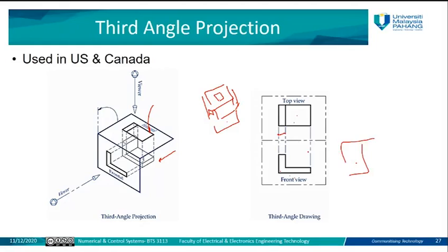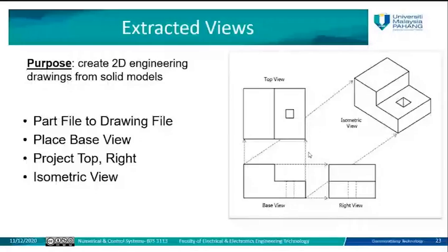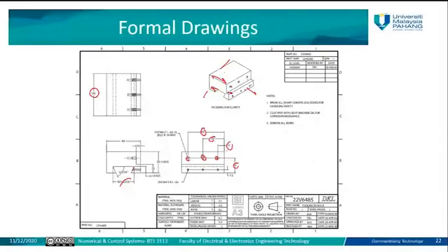But you cannot mix third and first. As you can see here in the previous example, they call it third angle projection. It is already indicated, this is the third angle. So it's not first angle. If it were first angle, the arrangement of the views would be different.